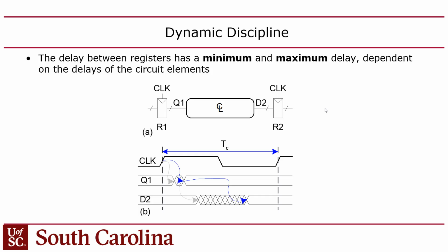Now the problem though is all of this dynamic discipline stuff happens at the gate level. But if the compiler fails to enforce the dynamic discipline, then you have to go back and look at your Verilog, right? But the problem wasn't in the Verilog directly, it was in the gates. But you don't know how the Verilog was translated into gates, yet the problem was in the gates. So you have to figure out how to change the Verilog in a way that when you resynthesize it, you have a shorter critical path, right?